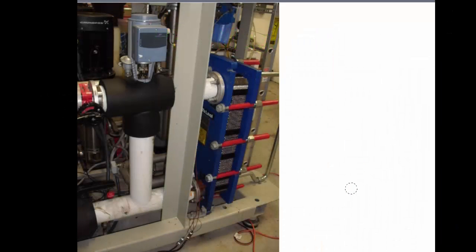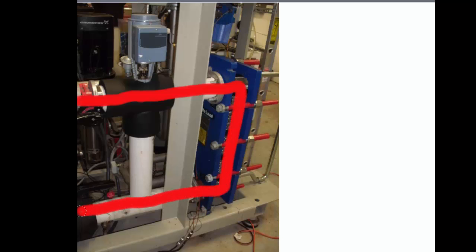So in this picture we have of the main coil cooling, you have your main coil chill water coming in this way. And when it gets to this 3-way valve, it has a choice. The 3-way valve can either close, which will force the flow through the heat exchanger and back down through the chill water return.